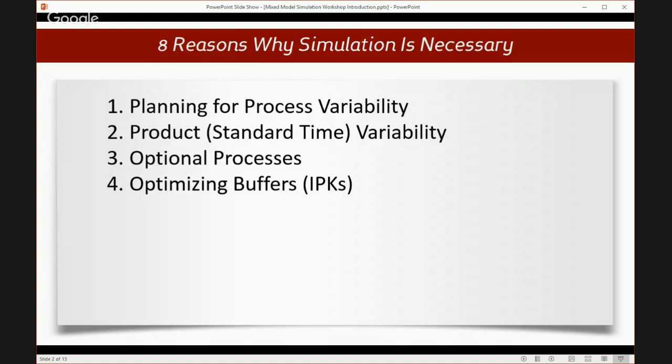And we know from experience that in a very short takt time environment, more than 1 IPK is normally necessary. And we have run simulation models in which you put 1 IPK, performance is X. You put 2 IPKs, performance goes up by 25% immediately. You put 3 IPKs, performance doesn't improve at all. So then you know you don't need 3 IPKs, 2 will do. So using a simulation model really answers the question, how many IPKs? Because you can try things out and choose the best number.